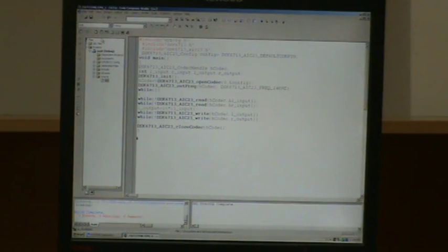All the steps are the same, but here only the code is different. All the things are the same, like including the header files, DSK6713 header file and .h file, codec file, configure, open and close. But here we have to define two inputs: left input and right input, left output and right output. In the case of external signals, line input means the left input should be equal to the left output, or the right input should be equal to the right output.